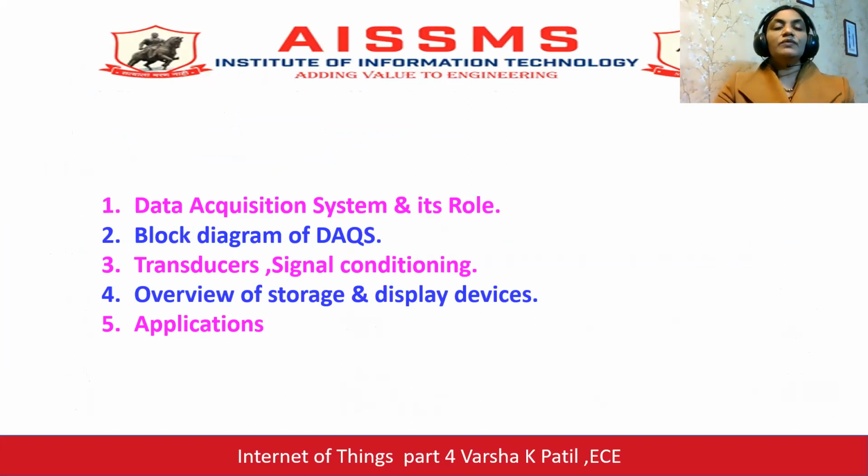The takeaway from this lecture is that we have seen the data acquisition system and its role. Then we have seen the block diagram of the data acquisition system. Then what is meant by transducer and signal conditioning, and some common signal conditioning circuits like the multiplexer and instrumentation amplifier. And then we have seen an overview of storage and display devices.